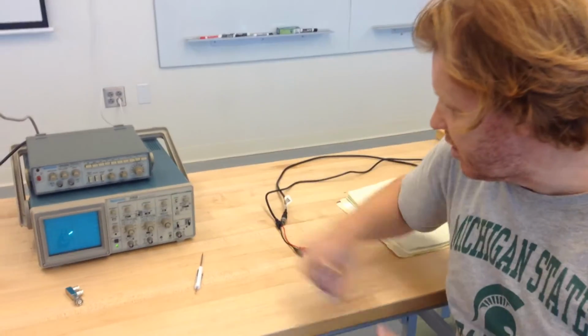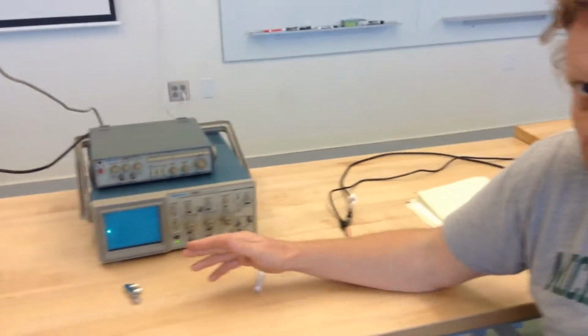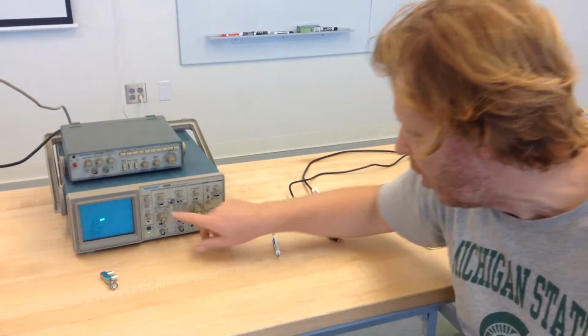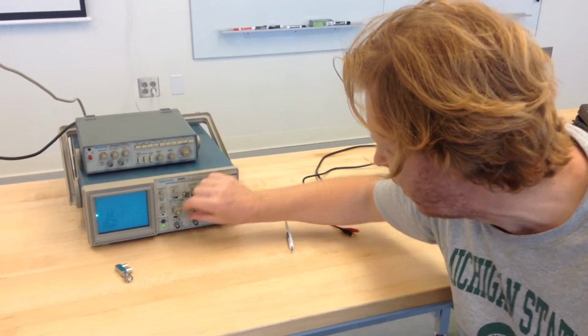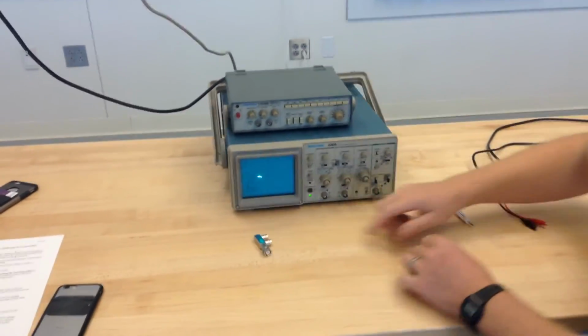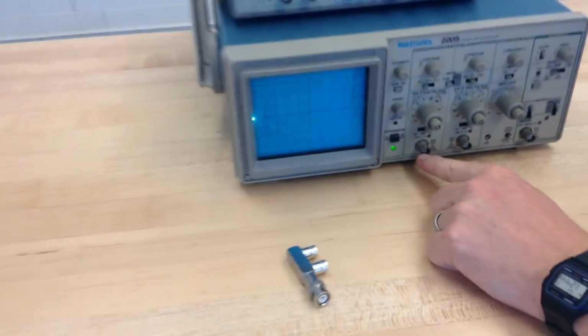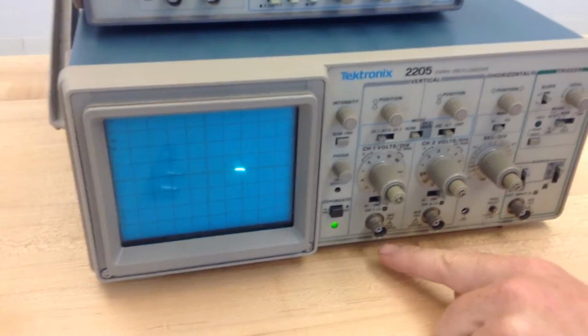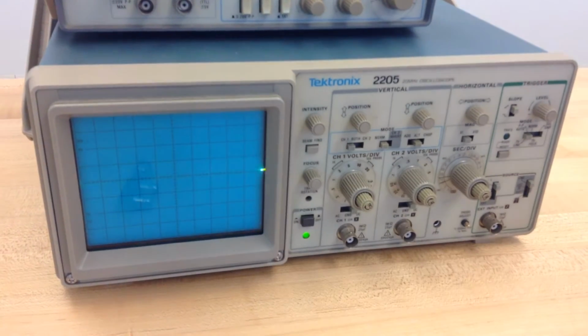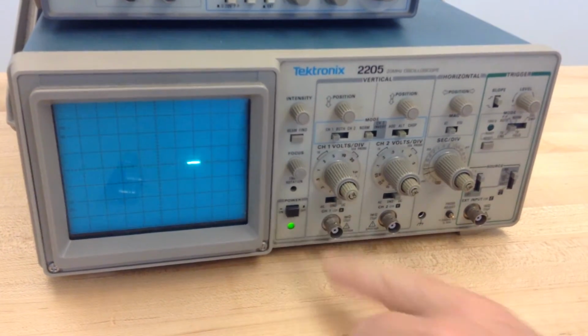Okay, so let's see what I meant by voltmeter. The uppy-downy scale is volts per division. Right now I have it at 0.5 volts per division. So I'm going to put it now at 2 volts per division. If I put into this BNC connector a voltage difference between the outside and the inside of 2 volts, this will be deflected by 1 division because it says 2 volts per division.